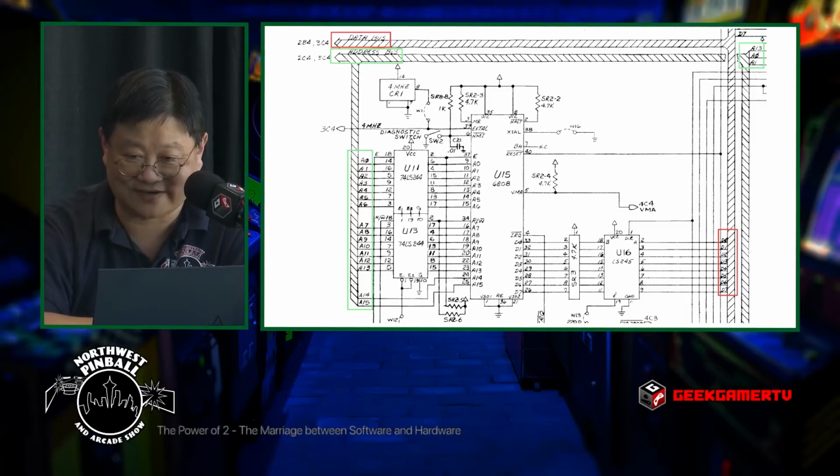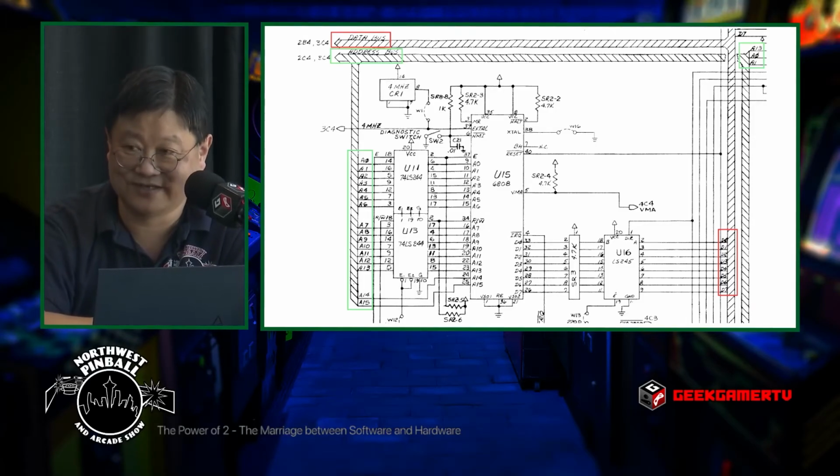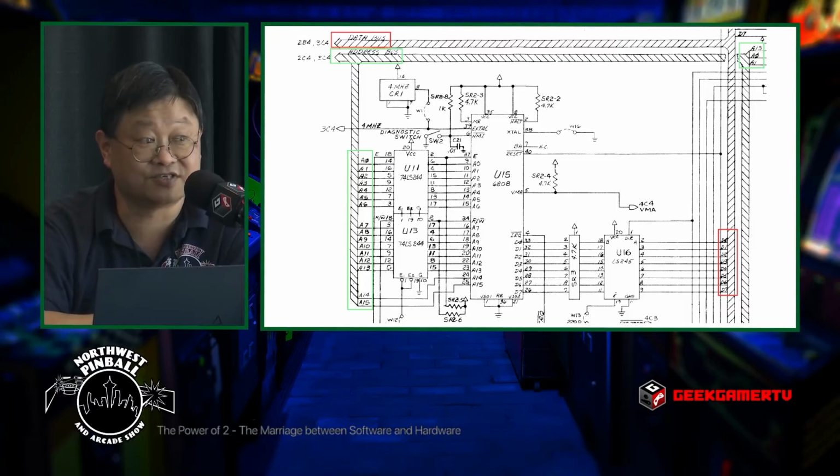In this diagram, they've even kindly crosshatched them in opposite directions, so you know which one's address and which one's data. And it's very consistent. The green is the address and the red is the data. And you can see where the signals come off of the bus that they've put this line and labeled each individual signal bit that's come off the bus. The data bits almost always come off together because they're grouped as 8 bits of data. The address bits often come off in different places depending on what signal the logic is interested in.